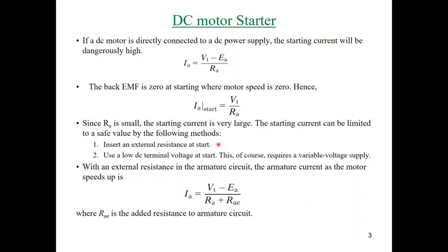However, in modern or advanced drives, we prefer the use of reduced voltage by means of a DC chopper, because as we described before, to perform starting, speed control and braking we can use only one power electronic device for all of these functions.